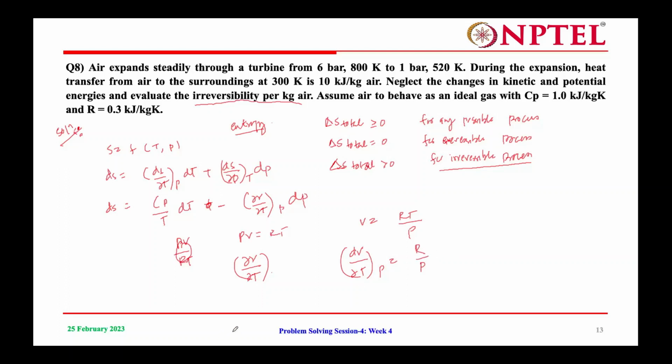Right? Now put this value in this expression, which is equal to ds = Cp dT/T minus R/P dP, right? Now integrate these expressions from state 1 to state 2.